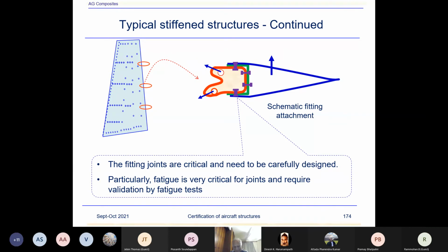Sir, just one question, sir. Is the fatigue life difficult to decide because of the preload relaxation which is happening, or something like that? Because when we preload the fasteners for CFRP, they undergo relaxation, right? The preload will be relaxing over time. Is it because of that?